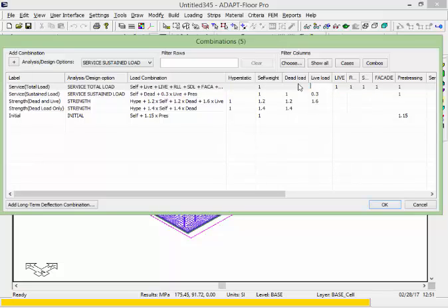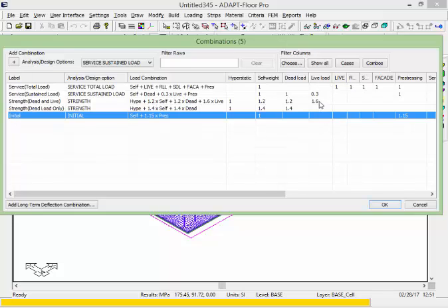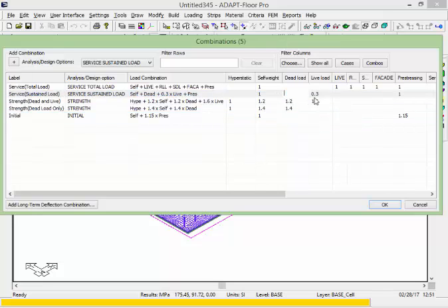There's no load that is actually assigned to those load cases, so there would be no harm in keeping the factor. But if someone was to come and review these combinations, they may have questions about why there are 2 superimposed dead and live loads included in the same combo. So we'll get rid of those. And now we'll come here and just add some factors to the loads that were brought over from Etabs.